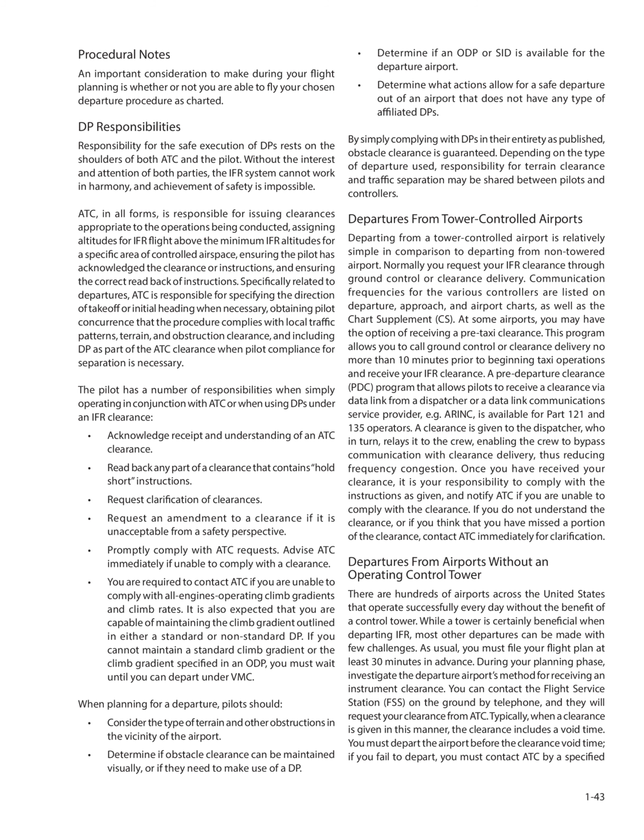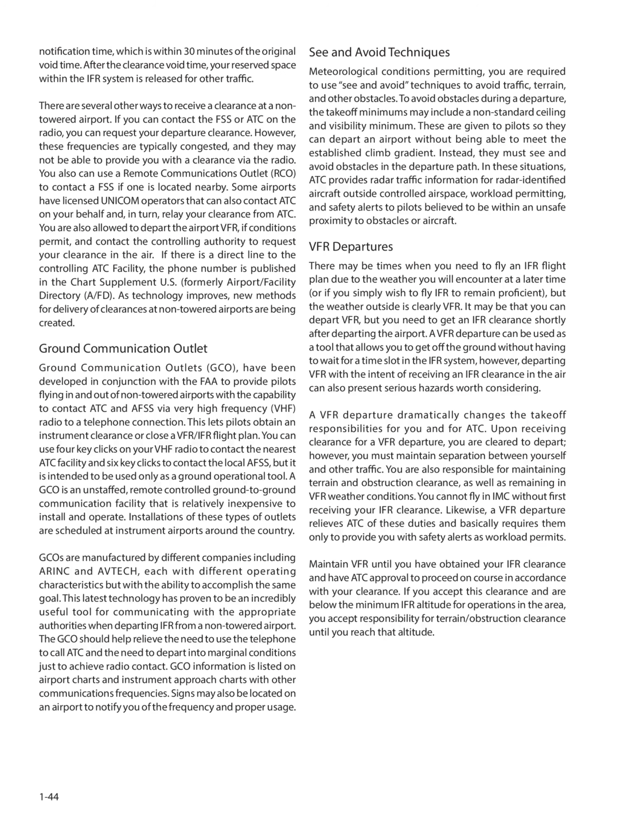If you fail to depart, you must contact ATC by a specified notification time, which is within 30 minutes of the original void time. After the clearance void time, your reserved space within the IFR system is released for other traffic. There are several other ways to receive a clearance at a non-towered airport.